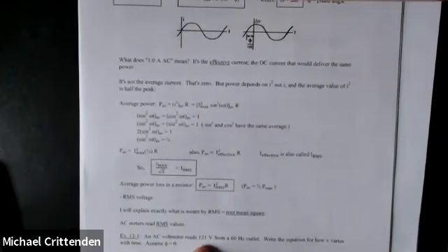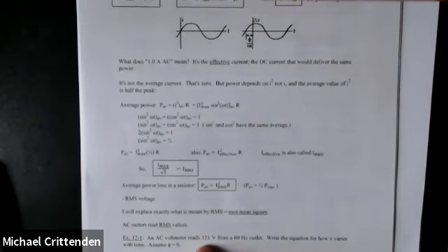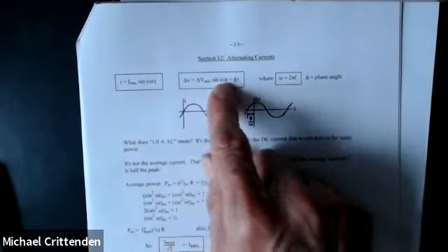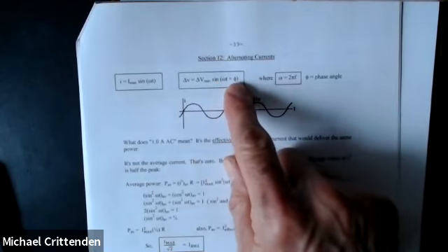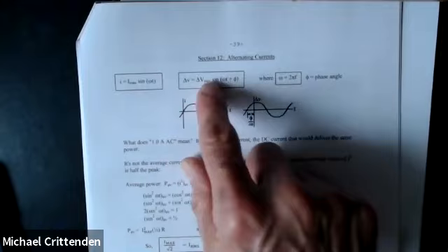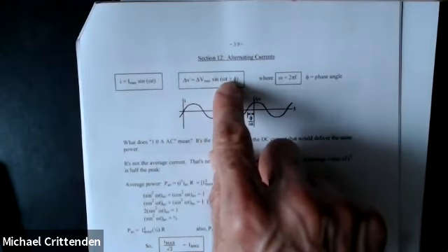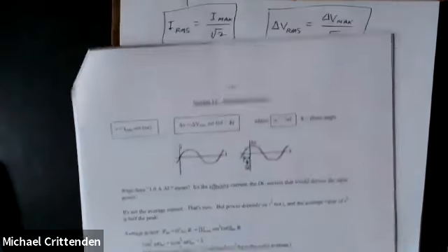And let's say at this particular house, it's 121 volts you've actually got instead of the 120 that's the target. So from those numbers, basically all it's asking you to do is go up here to the top of the page, and assuming that the phase angle is 0, it says that in the question, just fill in numbers for everything to the right of the equals except for t, so that you've got the voltage as a function of time.